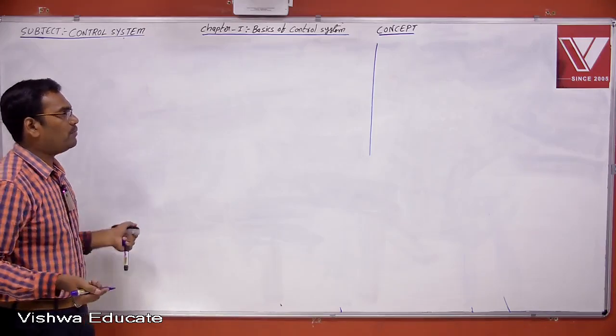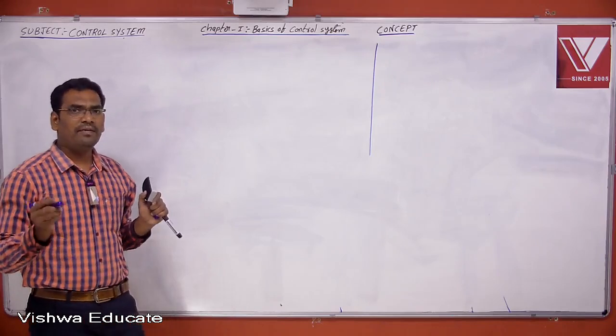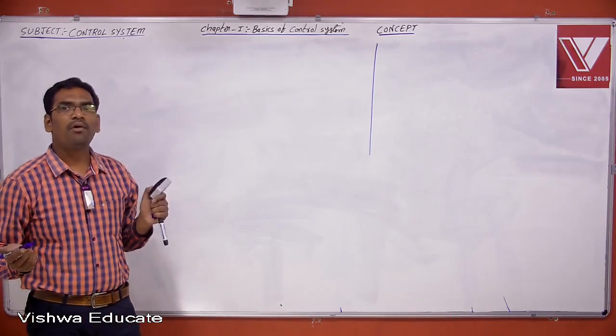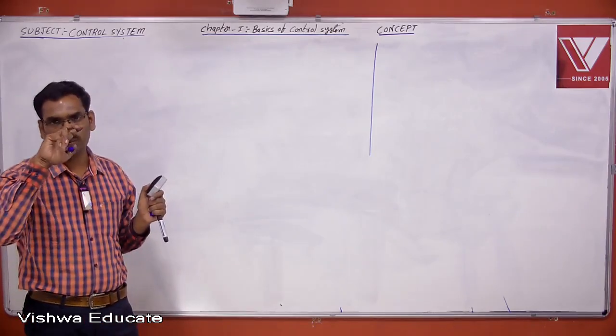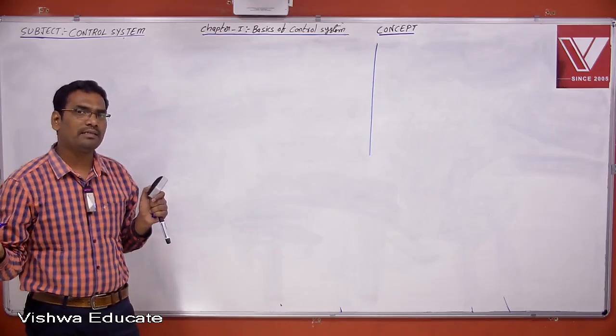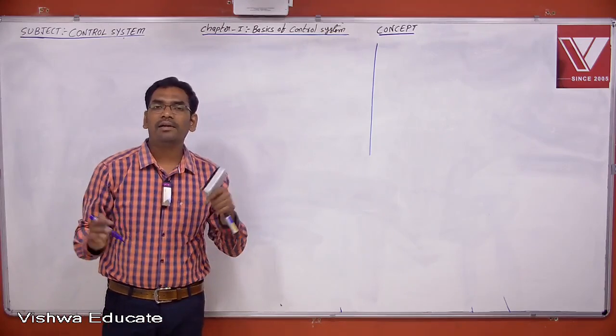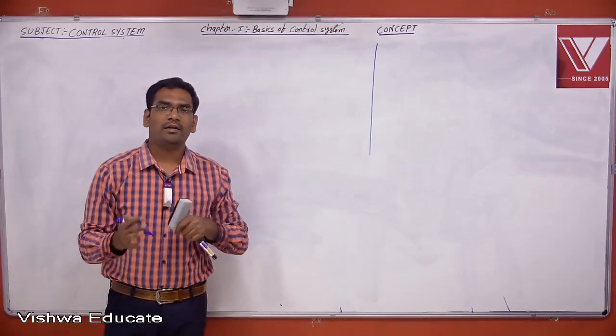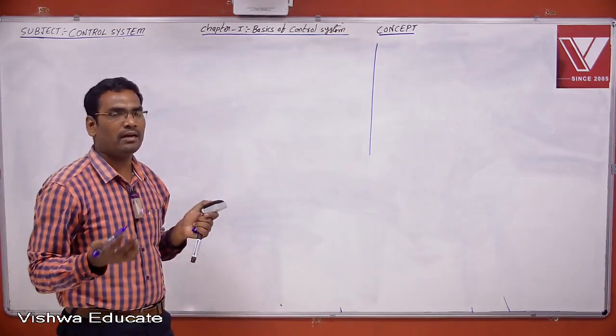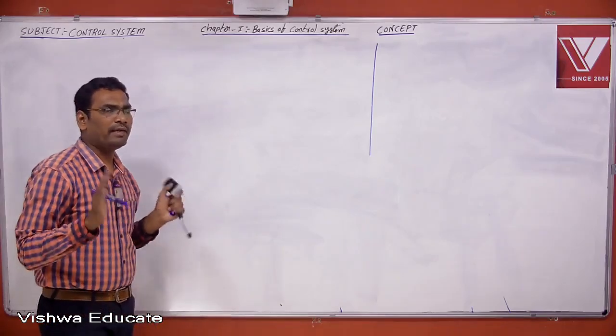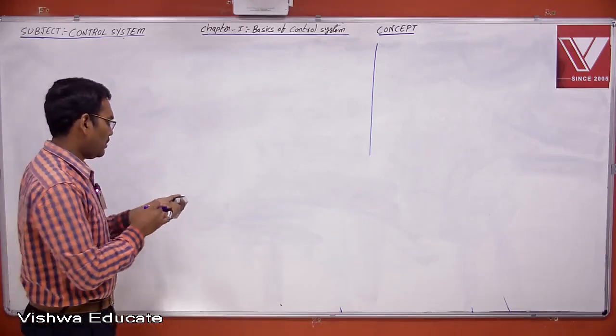Now what I am doing is giving different pole locations in the S plane. What we studied so far is only two cases: when the pole lies on the left hand side it is stable, and when the pole lies on the right hand side it is unstable. Now we will take all the combinations, and see the system behavior, response, time constant, and all the parameters.